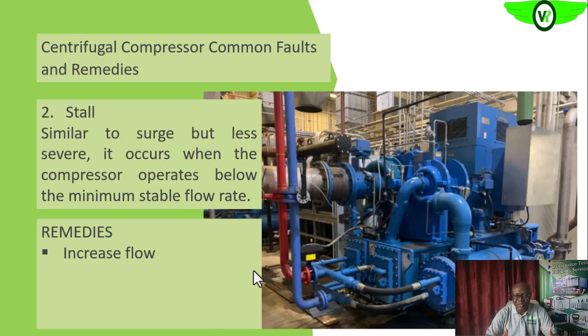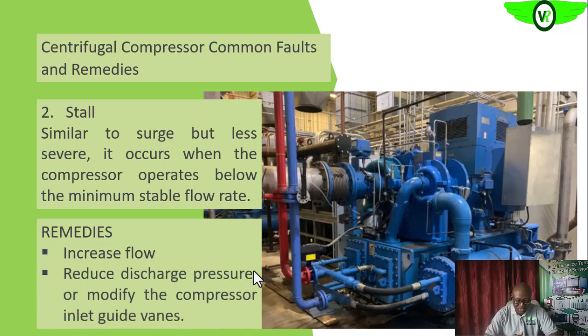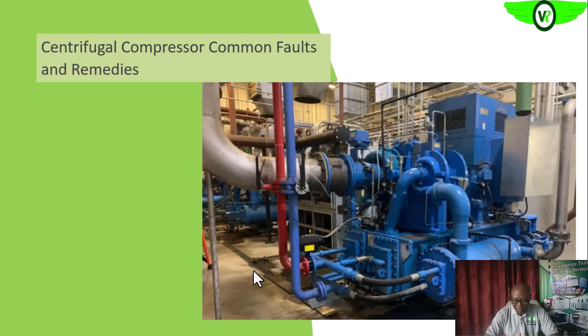Then we can also control the inlet guide vane to adjust the amount of gas that is administered into the compressor. So we can do all of that: reduce the discharge pressure, modify the compressor inlet guide vanes, as we saw earlier, to control the amount of gas that is administered into the compressor.